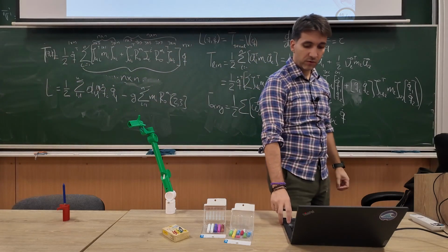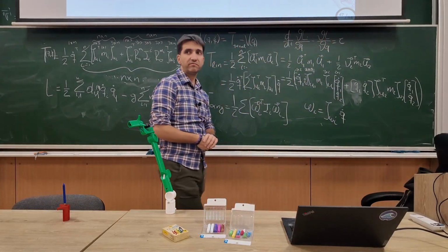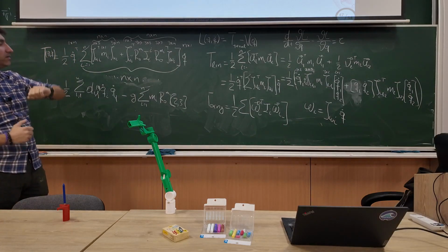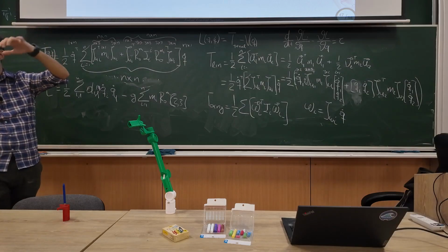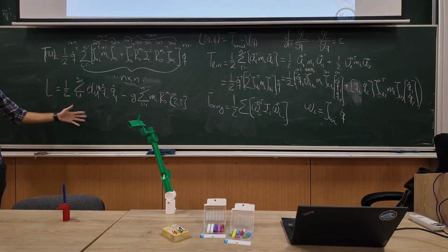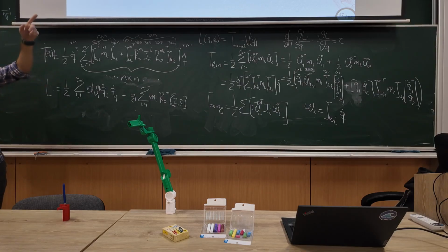All right. So let's derive. So let's calculate this. Now, q is a vector, right? So I have to do a derivation for q1, q2, q3, q4, qn, right? And I will get an equation for the motion of q1 with the input of tau 1, which is the torque at joint 1. Another equation for q2, another equation for q3. So I will have basically a system of differential equations, because each one of them is a differential equation.